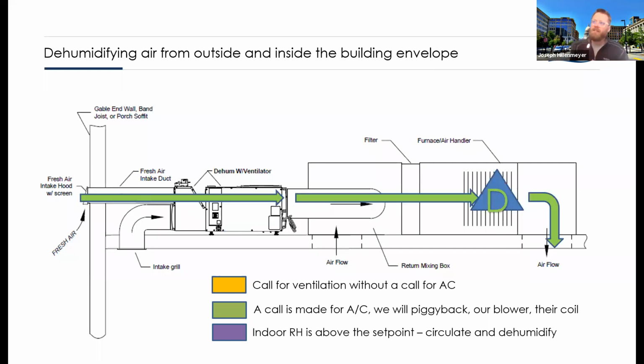If there is an AC call, we'll still use the ventilator's motor to bring that air in, but then we'll use the air conditioner to start conditioning that air. So again, we're piggybacking when we can. We're using the available equipment to do the job.